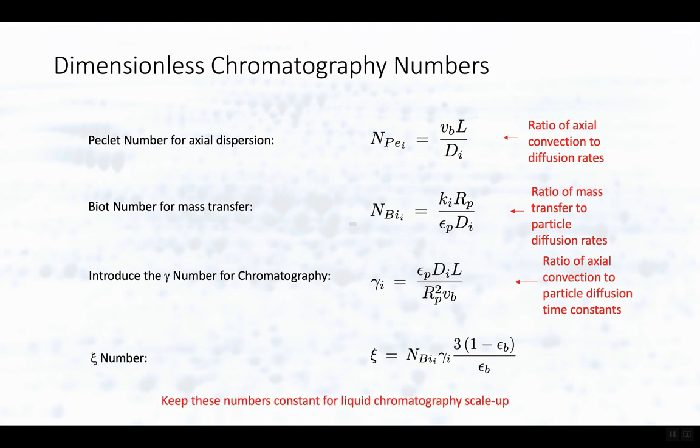All right. The key, though, is we've defined the chromatography model in dimensionless terms. It doesn't matter how big the column is. It doesn't matter how fast we're flowing down the column. It doesn't matter what the mobile phase is, because we've taken diffusivities out of it.